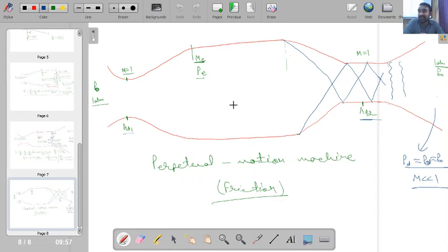So what we are expecting is, as I told you, that if I use a normal shock wave then the pressure loss will be more, but if I use an oblique and normal shock wave then the pressure ratio will be less. So I am expecting that in this situation I will have a slightly smaller pressure ratio in comparison to what we discussed for a normal shock and a diverging section, which was giving us for that particular situation the least pressure drop, the least pressure ratio.